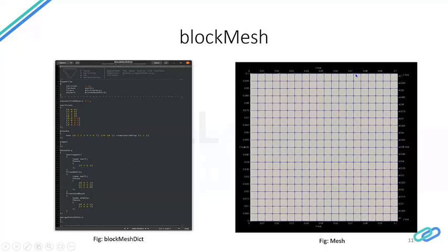Top wall right here is considered as a moving wall, and it is given the type wall. In cavity flow, the top wall moves at a constant velocity, and the interaction of the moving of this wall is then studied over the flow inside this cavity. A good example to visualize this particular phenomenon would be, let's say, if the skin of an aircraft's wing is taken away, there are several holes inside on top of the wing, and flow over that will simulate a flow in a cavity.